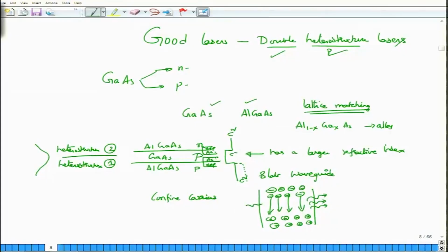Okay, with one noise photon that goes in at the beginning, you may actually start to get a large number of photons, and when this optical mode is reflected further back and back and back, you will see that this mode continuously goes through the active layer, causing the electrons from the conduction band to transition into the valence band, and thereby giving off more and more photons.